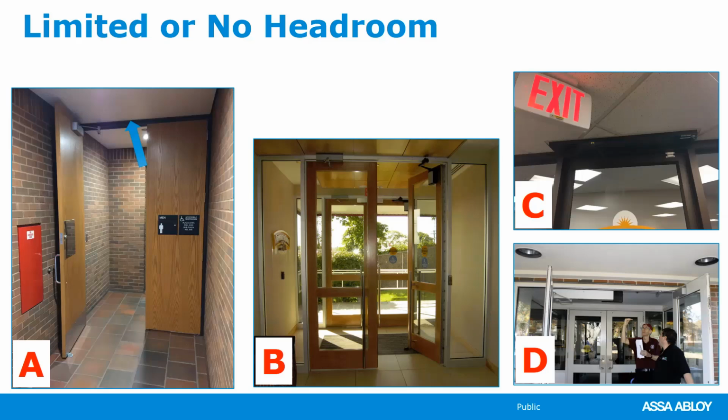Number 3 would be exampled in picture C, where the operator has been recessed into the ceiling. Certainly have to credit the installer with doing a nice clean installation, but the service on the unit may require removing the ceiling tiles that are replaced around the operator box. So not necessarily a bad installation, but certainly one that was challenging and may have some maintenance issues associated with it. Or B, the right-hand leaf, clearly a relatively straightforward door-mounted solution, standard brackets and fasteners that came with the Norton 5800 right out of the box. Easy to automate this door shown in B.